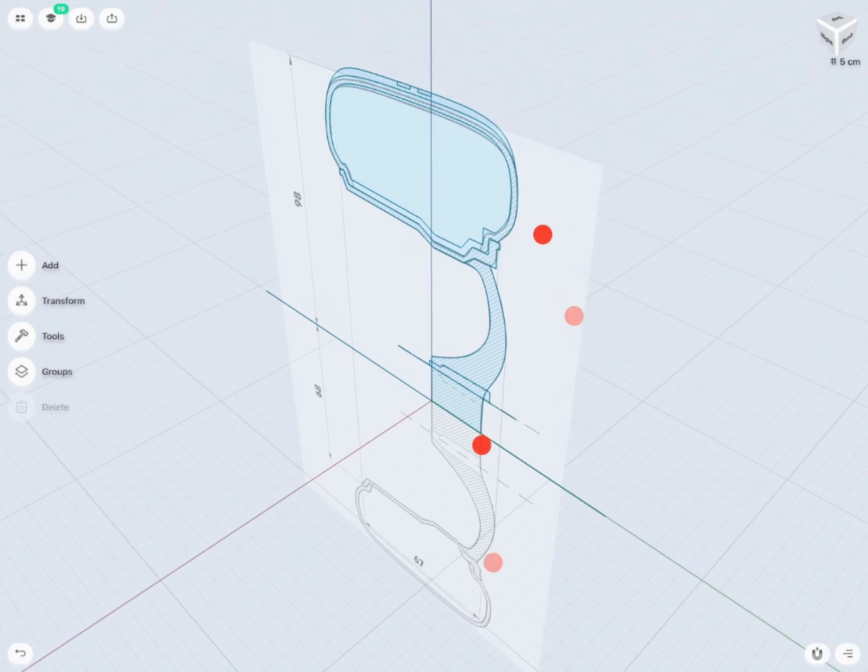I'm going to make a small fillet on the rim, as was on the sketches. If you select the edges and you want to make a chamfer, you have to pull your pencil up the screen, or if you want to make a fillet, you just need to go with your pen to the bottom of your screen. So this is kind of a tip for you.